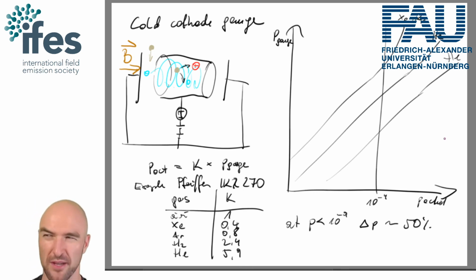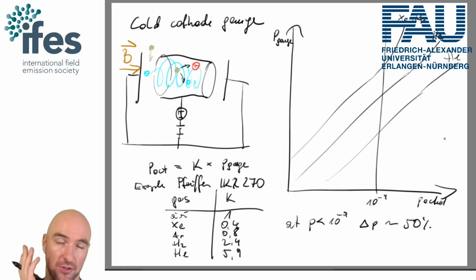So far, I think Chalmers has done that, but you always have the option to put a residual gas analyzer on your system, which can really help you figure out if you've got something outgassing. The problem with residual gas analyzers is they tend to be a source of residual gases. Might sound like a bit of a joke, but they can spit out some hydrogen. That's why, unless you have a specific question where you need residual gas analysis, it's usually not a great idea to put one in. Also, they're big, they have a finite lifetime, and they cost a lot of money. That's why not a lot of people have them.